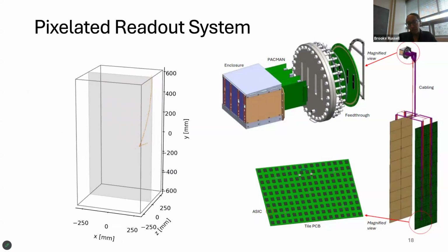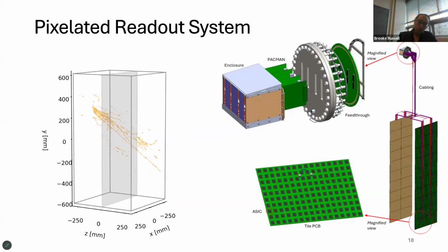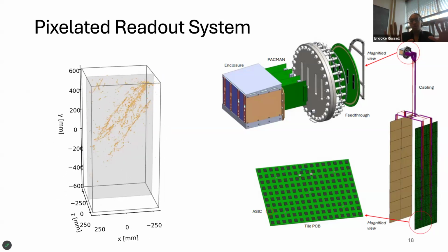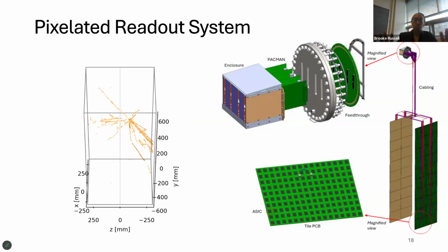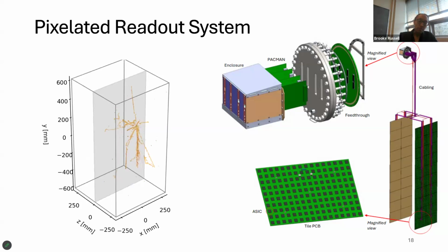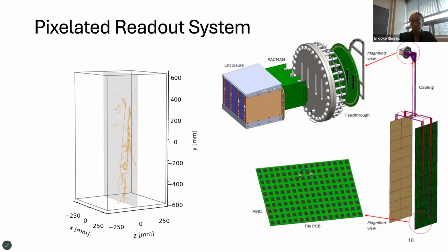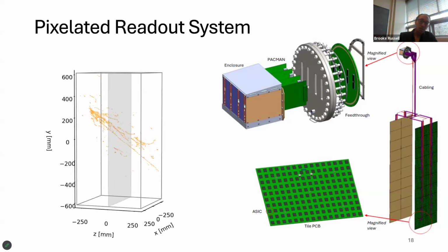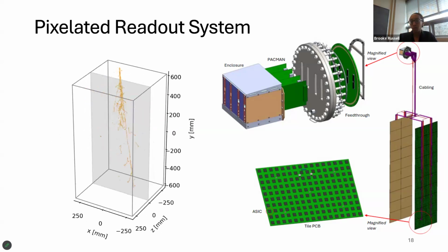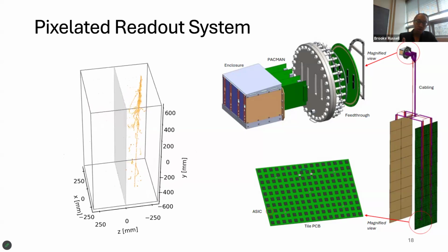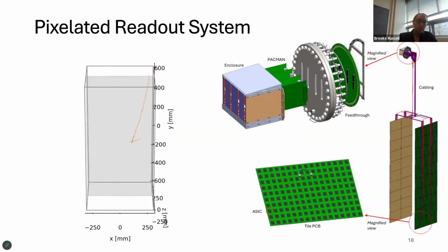And we've created an end-to-end charge readout system, which includes the ASICs, large format printed circuit boards, which are the actual anode planes in our detector. These circuit boards are tileable such that we could instrument any area of any dimension. And then we have cryogenic cables connecting to the outside world. So those feed the signals to our warm electronics. And those warm electronics are connected via Ethernet to our data acquisition computers.